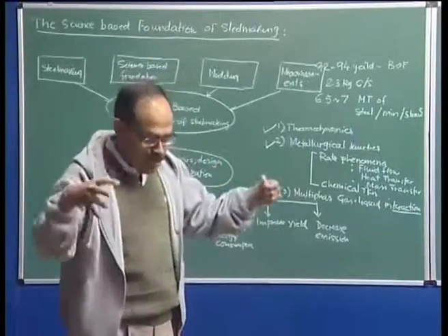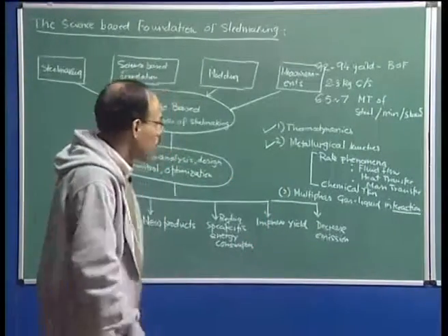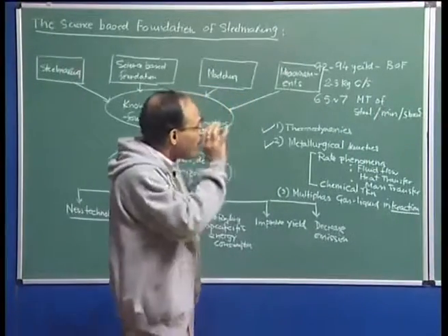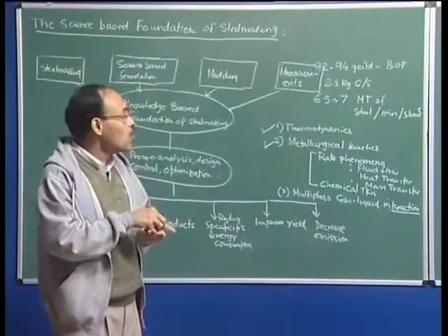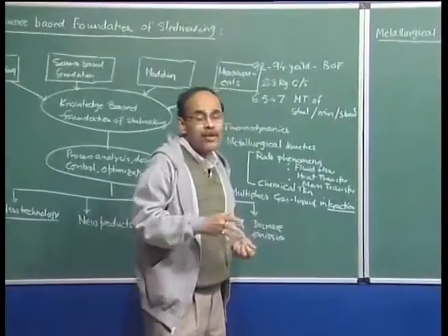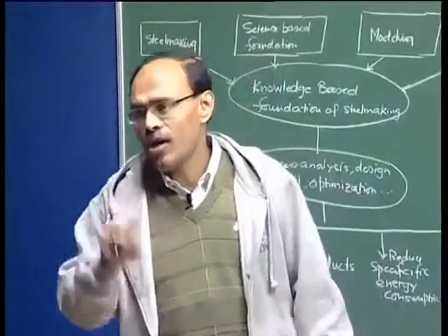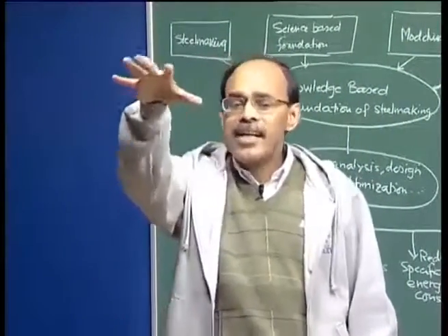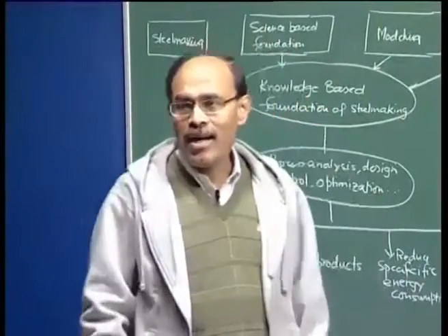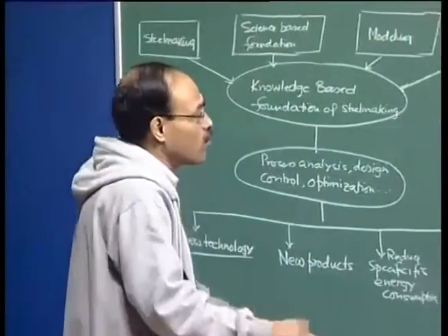If the reaction reaches equilibrium at a certain temperature and pressure, what is the composition of the system in terms of its carbon concentration and oxygen concentration? So all these equilibrium calculations we wish to perform in the context of steel making. For example, I have a slag and I want to find out how much iron oxide would be there in the slag in equilibrium with a certain given concentration of oxygen. So I will carry out an equilibrium calculation and find out the level of iron oxide content based on that equilibrium concentration.